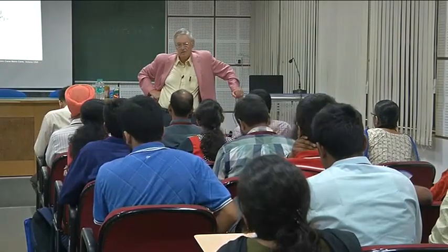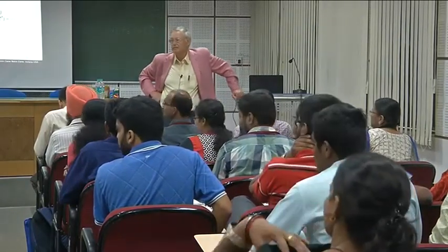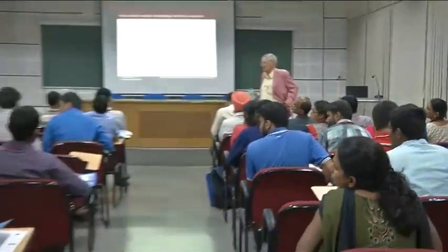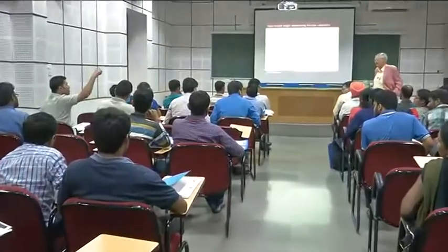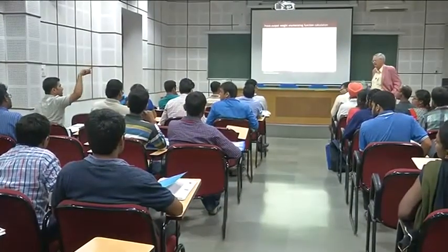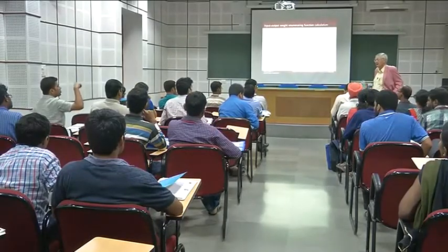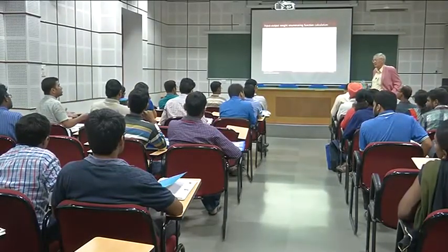Any other questions then? In finding this transfer function, from start to end state, we find the minimum weight. That's the free distance. So how does it help us to analyze the performance?